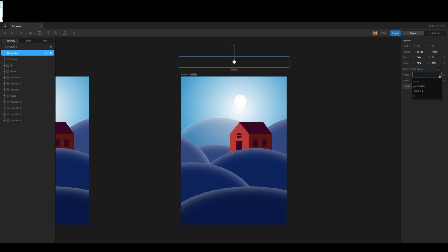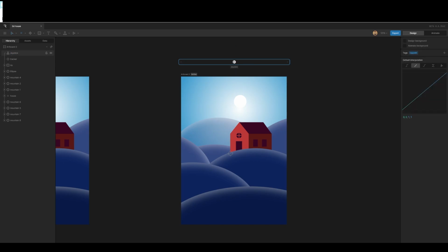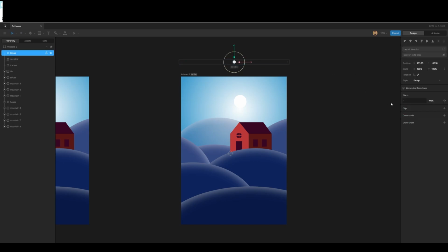And then for the x-axis, link our perspective here. And then we need a handle source. So press G and just create a handle source there. And just make this also a target and call this handle source or whatever you want to call it.